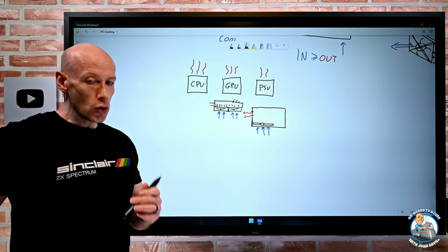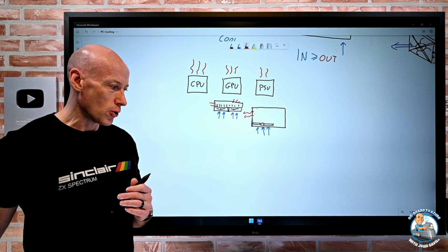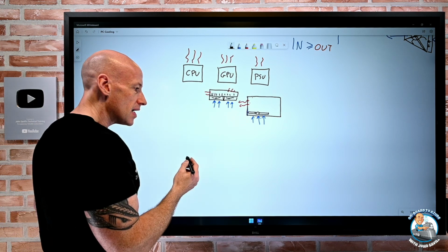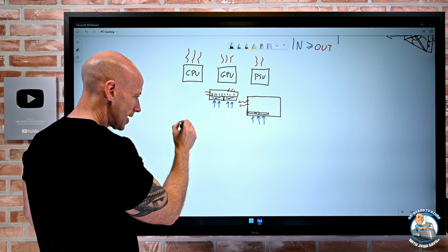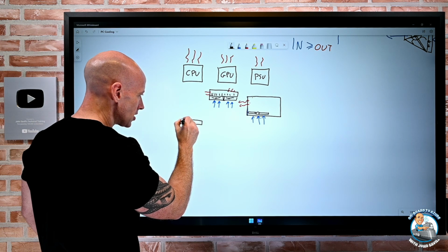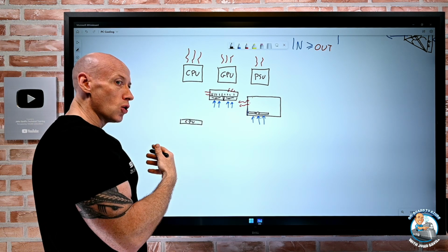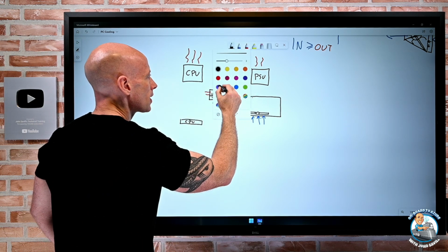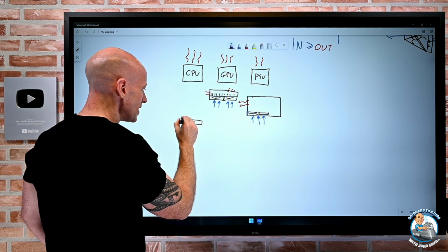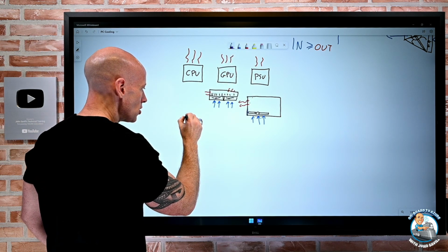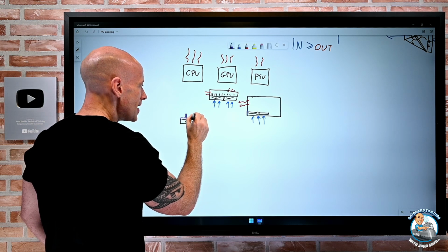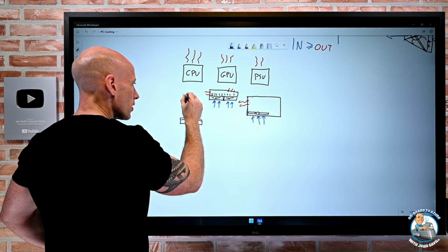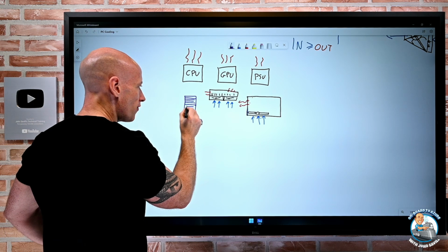So there are different solutions that we can apply to the CPU. The traditional one, if you get something in the box, and I'm rotating the direction now. If I think about this was my CPU here, so I'm now looking at it side on. There's a traditional heatsink. So the heatsink would basically sit on top, so it's covering the surface. Then you'll have some maybe copper pipes, and that's going to connect to a whole bunch of fins. So it's got a whole bunch of fins to maximize the surface area.